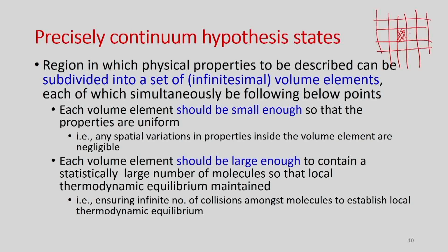And then from one control volume to the other, the property may change, and that property change is in general continuous, unless there is a solid and the nearby first layer is a fluid, with different densities of solid and fluid. There is a discontinuity, but the geometry has to be large enough for the continuum hypothesis to be valid for discontinuous surfaces as well, right.